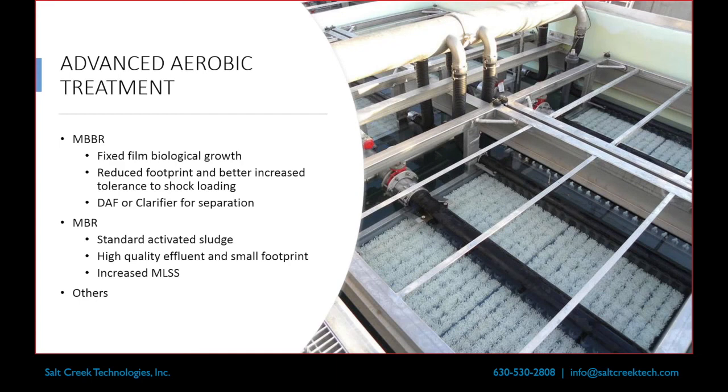What that does is it reduces your footprint by some amount. You can typically put a higher loading into that system. And then because that fixed film is a slower growing biological material, it typically stands up better to shock loading than an activated sludge system, just because you retain some of the MBBR. People say it has a memory of the shock loadings that it's seen in the past. So if you put something down the drain that's really not great, a lot of times there's still that biological material that can handle it a little bit better.